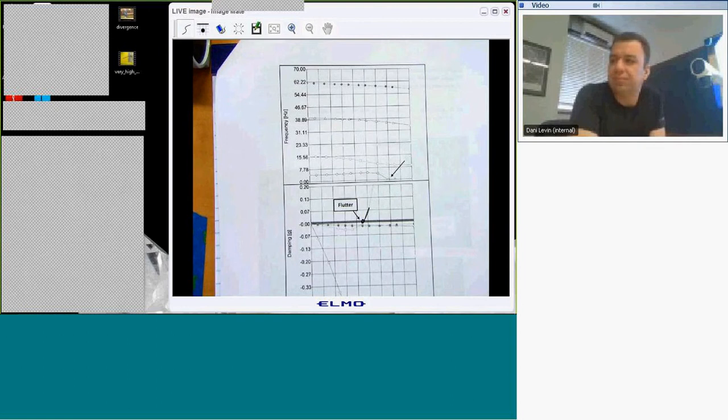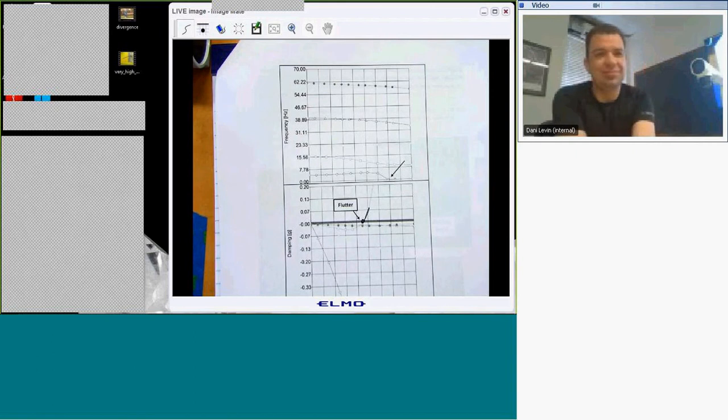Each aeroelastic mode is no longer a pure structural mode. It's a linear combination of the structural modes. Since you don't know ahead of time which particular structural modes will combine in a certain way to produce flutter, you need to include enough to make sure you haven't left something out. There's always the possibility you have left something out, and there are famous examples in the history of aeroelasticity when people left something out and then when they tested the wind tunnel model, it fluttered, much to their unpleasant surprise.